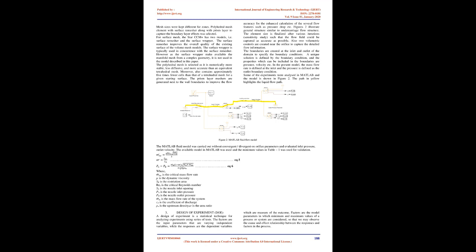2. General methodology. A simplified representative undercarriage shock strut continuous flow model, Figure 1, was developed with an orifice in the center to study the effect of parameters and their interactions during the constant flow of fluid from one chamber to the other through an orifice. STAR-CCM+ was used throughout for the CFD analysis.